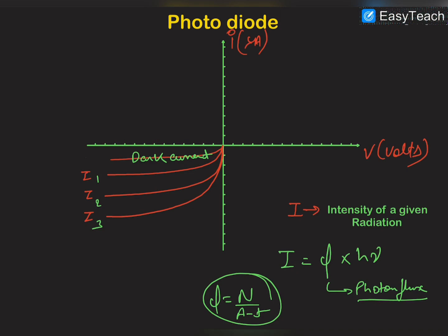So in this way, let us suppose we are using the diode as a sensor, and this current is 3 microampere. I'm not using the negative sign because I know that this is reverse current. If this is 3 microampere, then we can say that the circuit will trigger at this current.